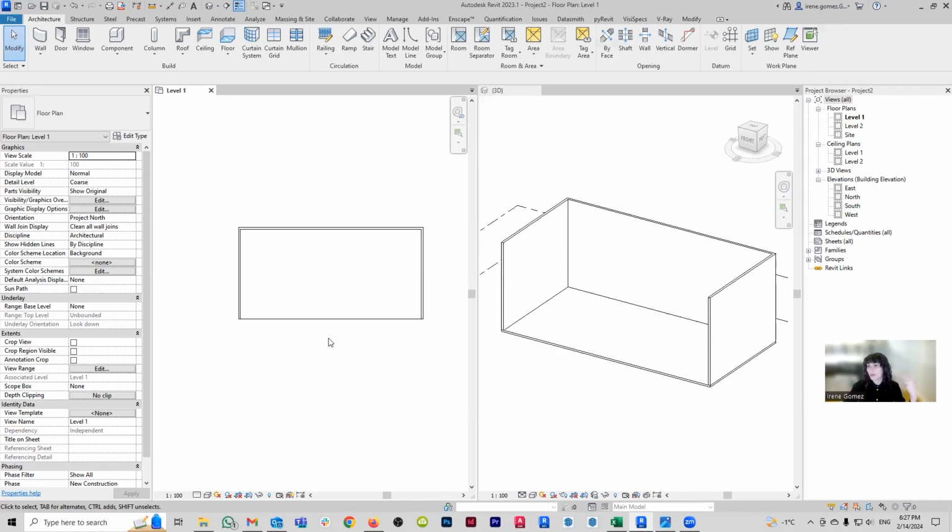But basically, what I'm going to do to make my life easier is work with the monolithic stair, and I'm actually going to start with a straight stair, just so I can plan a little bit what I want my stairs to be without having to worry about whether it's working exactly the way that I want or not. So I'm going to choose, under the Architecture tab, Stairs.